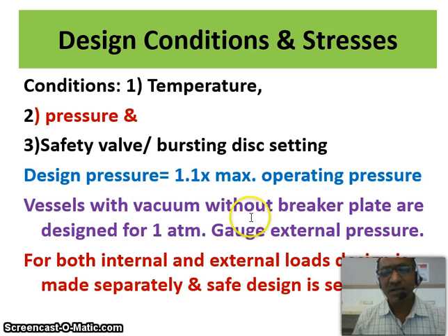So vessels under vacuum without breaker plates are normally designed for 1 atmosphere gauge external pressure, and for both internal and external loads, design is required to be made separately, choosing the design which will be safe for the intended application.